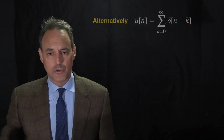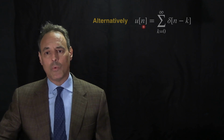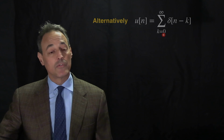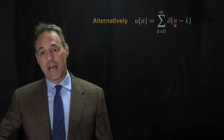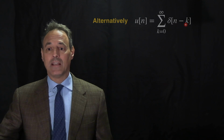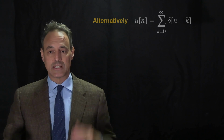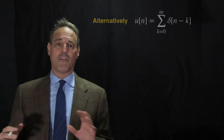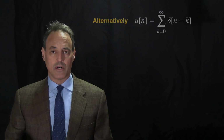There are alternatives to do this, right? Right now what we have here in the argument is n. We can always change this over to this notation instead, which is the sum starting from 0. Before I would start from negative infinity to infinity, but I can start from 0 and add this up to n minus k. So this thing will be 0 until k is equal to n, at which point this thing becomes 1. So the summation hits that 1, and that's a way of defining that step function. There are ways to define these just by shifting around the arguments inside of this variable here.